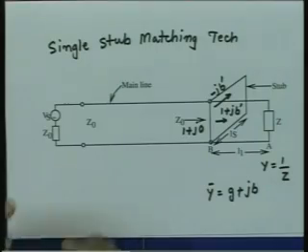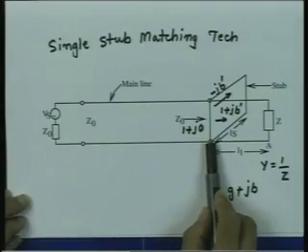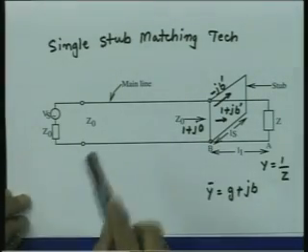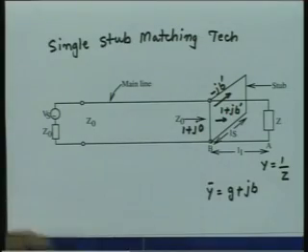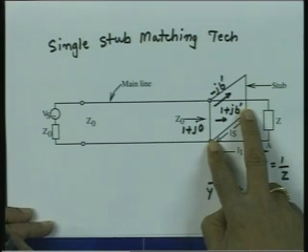Take a simple case. Suppose I am having a coaxial cable kind of structure. For connecting the stub to the coaxial cable, I have to drill a hole in the outer conductor of the cable, and make a joint with the center conductor and outer conductor. Once that joint is made, then by having some kind of shorting plunger inside the coaxial structure, I can change the length of the stub easily.